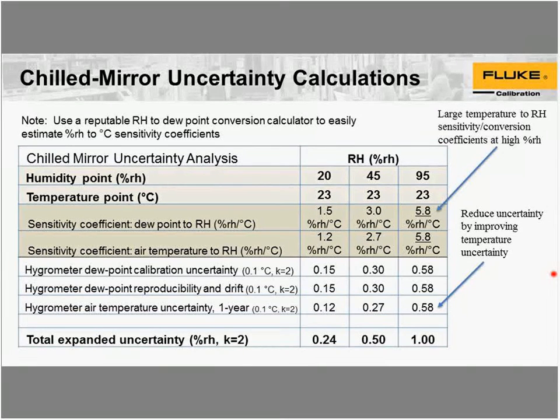Okay. Let's see. What's Sen 5128A? It's the Rotronic sensor. We showed some pictures of it. Let's see. Do the recalibration of the 5128A. There is a calibration method described in the manual. Basically, it involves using a chilled mirror hygrometer. But to get a good TUR on that, it gets a little tricky, especially at the higher humidities.